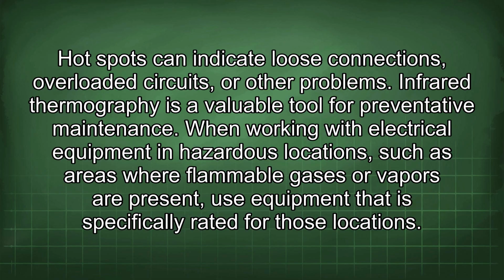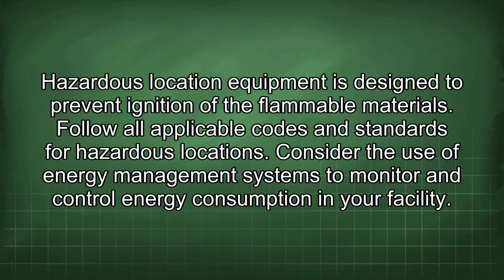When working with electrical equipment in hazardous locations, such as areas where flammable gases or vapors are present, use equipment that is specifically rated for those locations. Hazardous location equipment is designed to prevent ignition of the flammable materials. Follow all applicable codes and standards for hazardous locations.